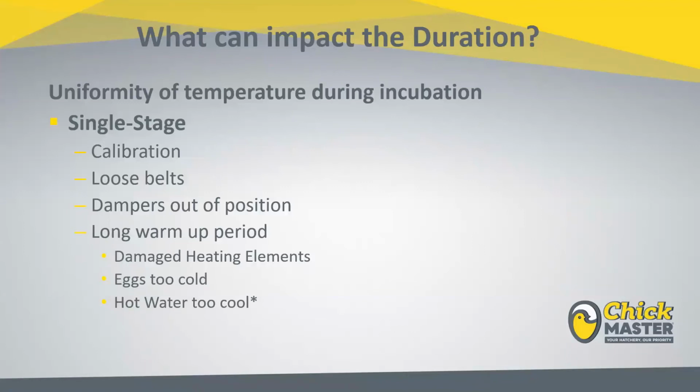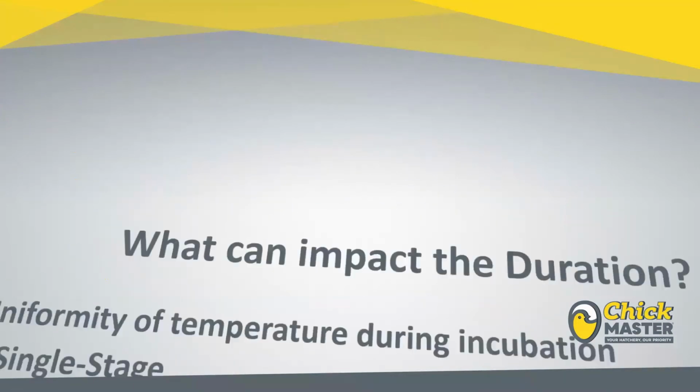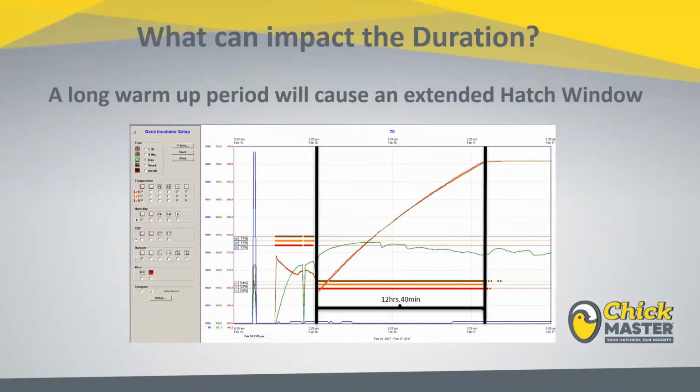So an adequate range for hot water heating is anywhere between 150 degrees Fahrenheit up to about 175 to 180 degrees Fahrenheit. That's usually a really good range. Anything above that, you can get into some too-much-heat issues, and anything below it just extends the warm-up time. So we look at that on a graph.